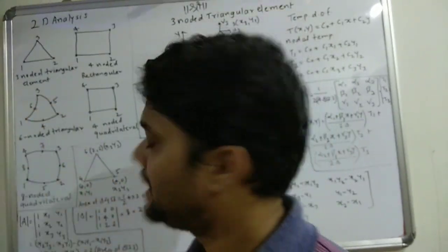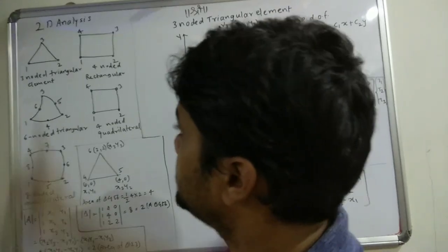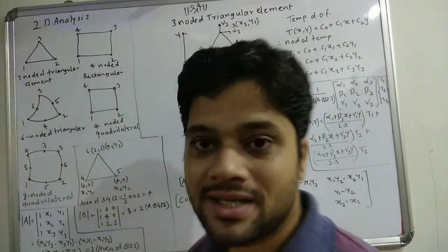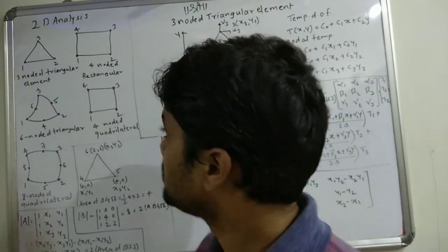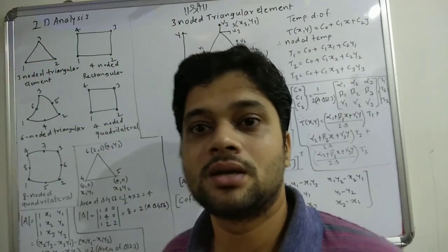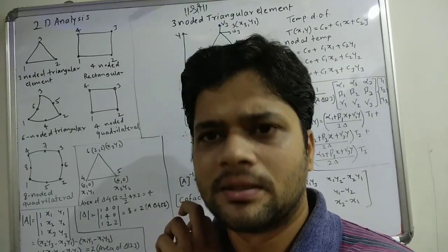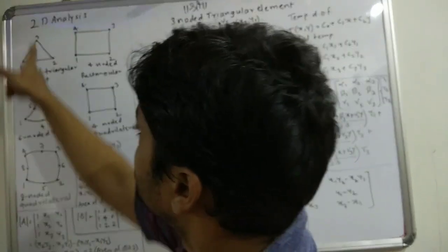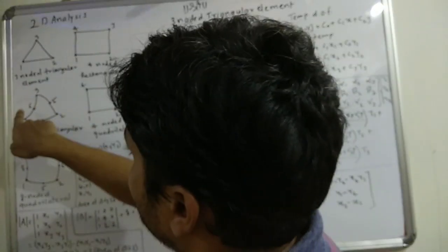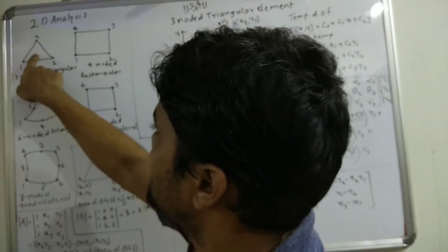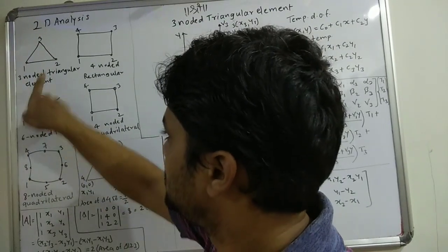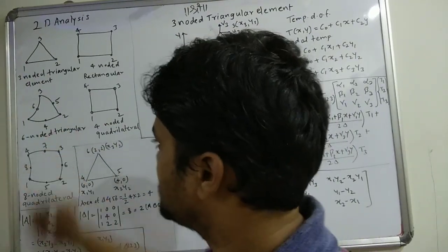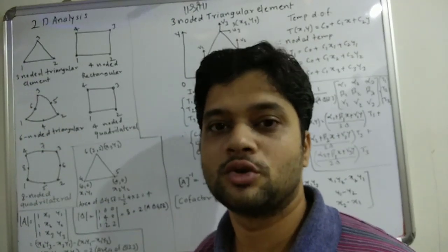Similarly, I can add complexity in the triangular element. On each edge, as I can see, there are only two nodes of the triangular element, so the nature of that triangular element is still linear. If I add more nodes, let us add one node on each edge. That will give us three nodes on each edge of the triangle, and that becomes a six-noded triangular element.